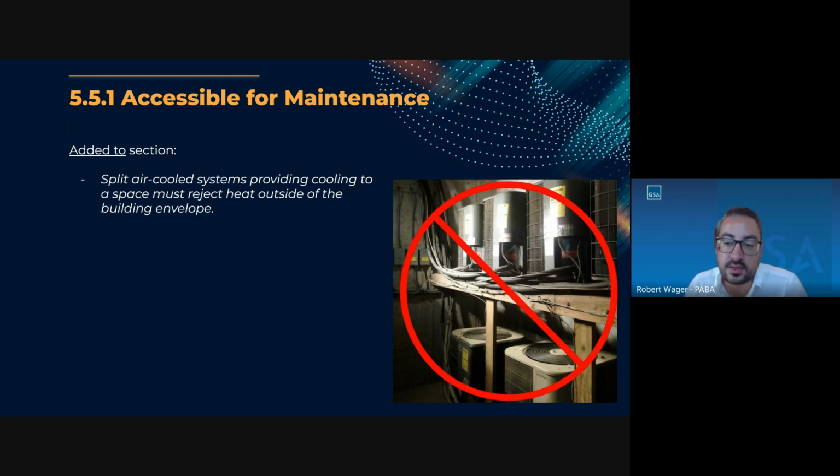Air handling units that are just sourcing ventilation air from the outdoors most certainly can be located above a ceiling plenum, because the ductwork that is getting that outside air is sourcing it directly from outside. The point of that comment was that we're not locating condensers that are intended to be outside above a ceiling plenum and rejecting heat to the ceiling plenum and not to the outdoors. Yeah, and as Greg rightly pointed out, a condensing unit that's designed to be ducted can be located inside.